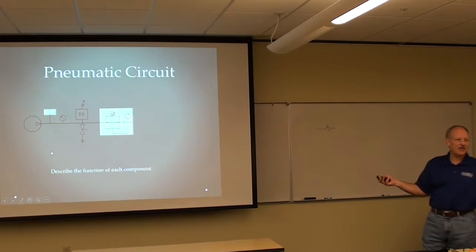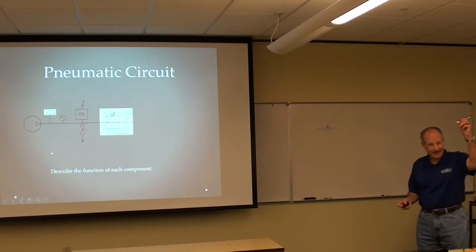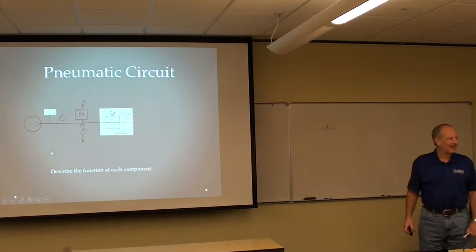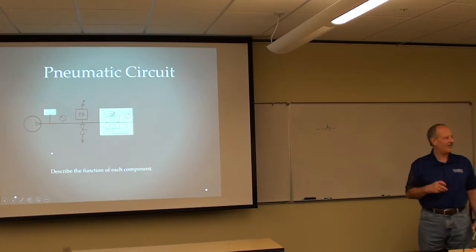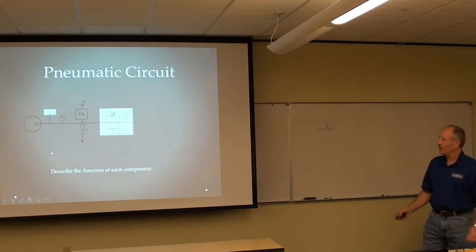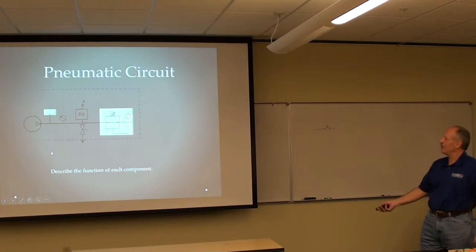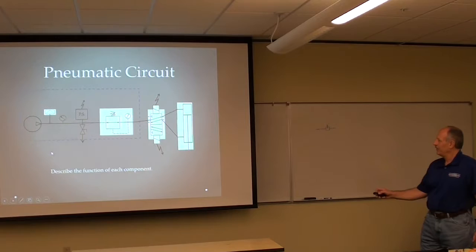So that's one of the disadvantages of pneumatics. If I just want to put this cylinder on, it means I have to add all of this stuff. You don't always have to have the compressor on board, and I'll talk about that in a few minutes. Okay, so that's what that circle represents. Here's my solenoid valve, and here's my cylinder, right?